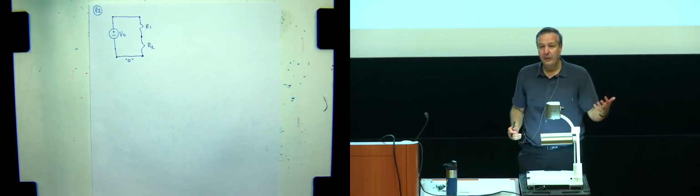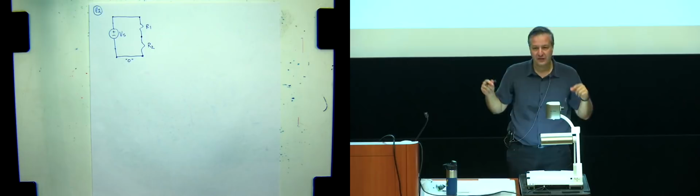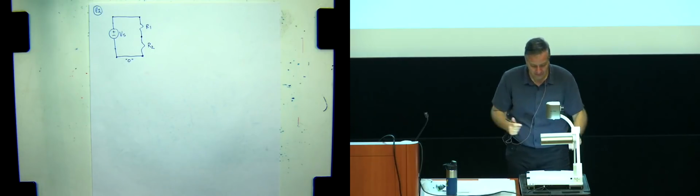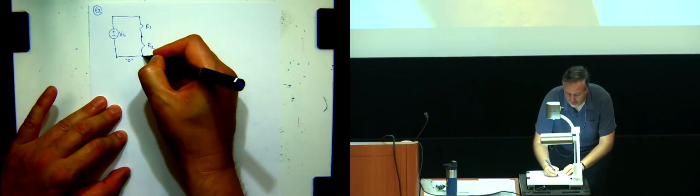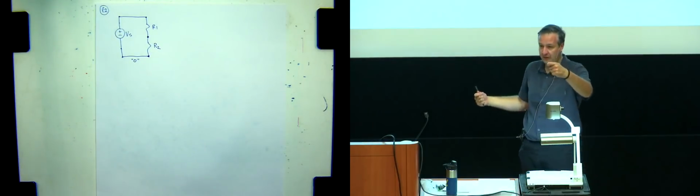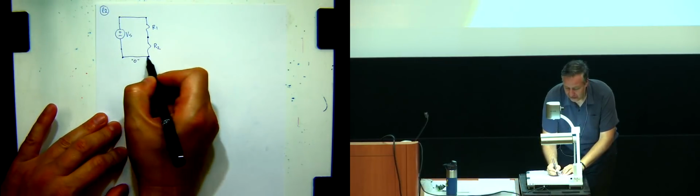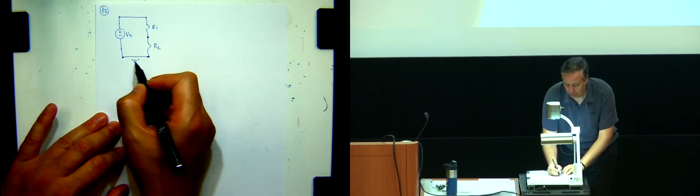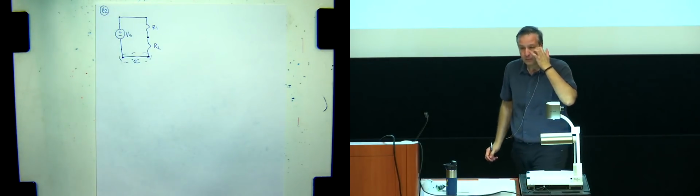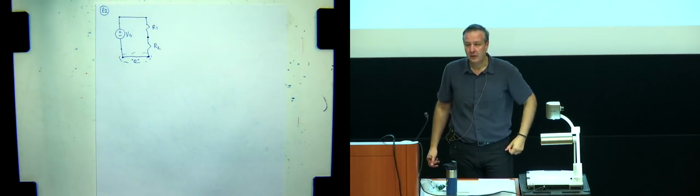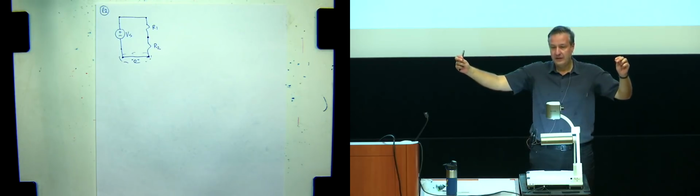And then remember what we talked about last time, just for people who are confused about wires versus junctions versus nodes. If this element, R2, has 2 junctions, 2 ends of the element, this VS also has 2 ends. This here is a wire. But note that I've labeled this whole region as a node, simply because that whole wire is equipotential.